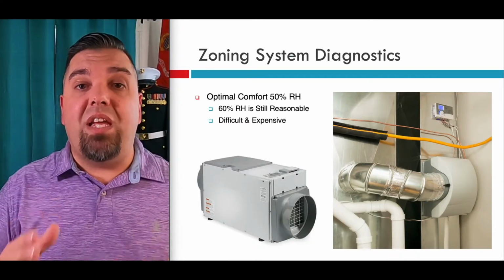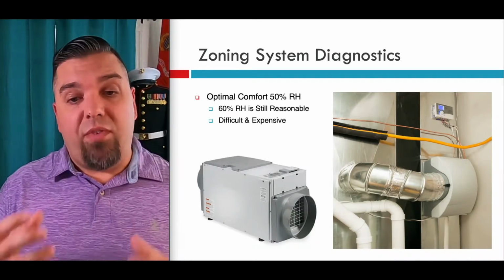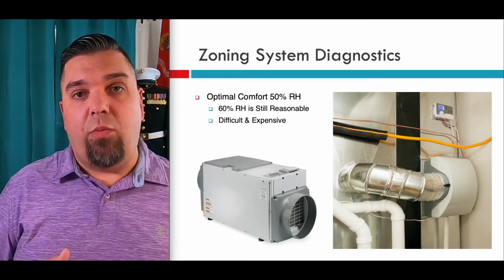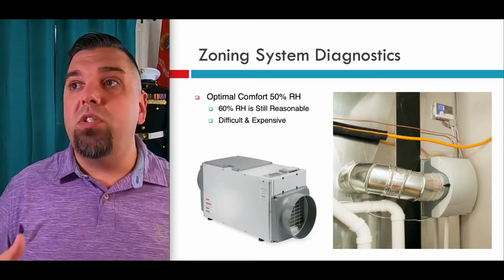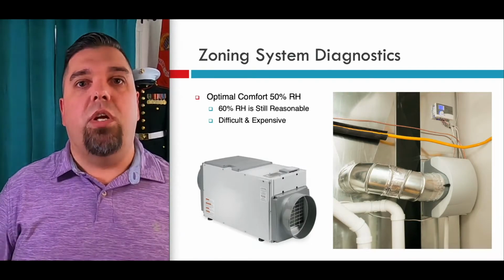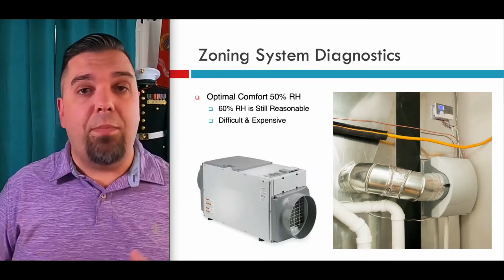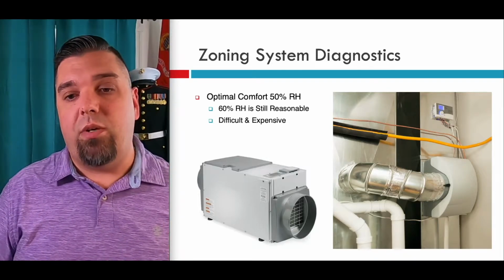But think about how that system is going to maintain that humidity. Obviously, when we're talking about dehumidifying, we need a whole house dehumidifier in most applications, let's say in the Northeast. If you have a basement that's below grade, you need a dehumidifier, probably a whole house dehumidifier. You're not going to be able to keep up with those little space ones, all right?